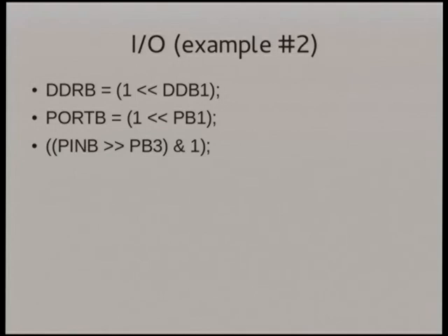So that means you can actually rewrite it a lot neater, and now you can actually see that the values make sense. Because it's all binary, you can just do a binary OR to mush the numbers together and pack them into the same byte, so you can do more than one thing at a time, which is something that you can't easily do using the Arduino libraries. You have to do, I'm going to do a digitalWrite, and a digitalWrite, and a digitalWrite to set 3 pins. With this, you can do all of those pins in a single port in one instruction.